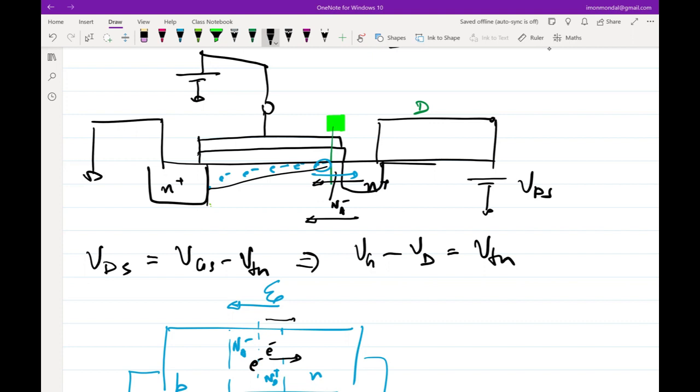Yes. So essentially what he is asking is, now we say that there are no electrons, but there is a current flow, which means there are electrons. There is a dichotomy between these arguments, right? So yes, indeed you are correct, but note that all these are approximations. Even though when we say that it's depleted of everything, there are always electron and hole pairs getting generated. Just that their concentration is not higher with respect to the ionized impurities. So it's basically the game of which is higher, which is smaller, right? When you have a depletion region, it doesn't mean that there are no mobile carriers. There are, but their concentration is much lesser than the ionized impurities.